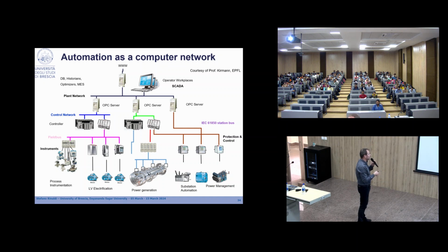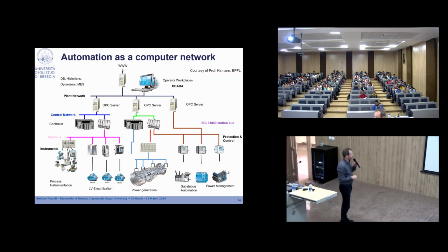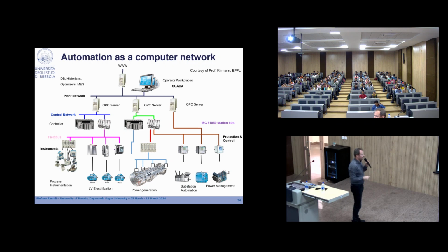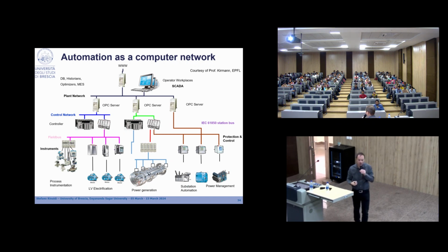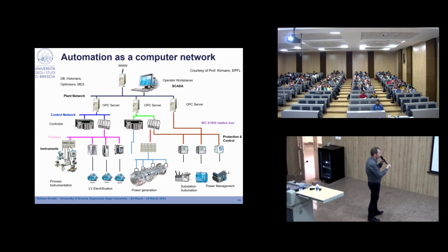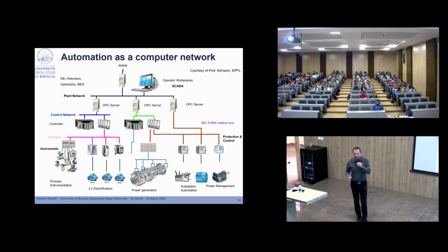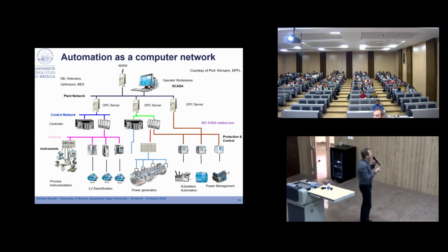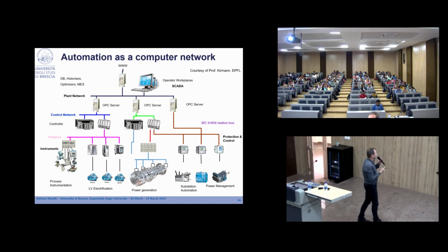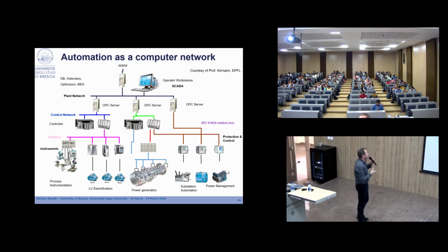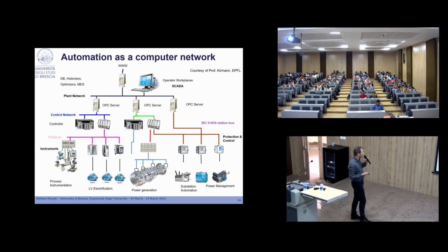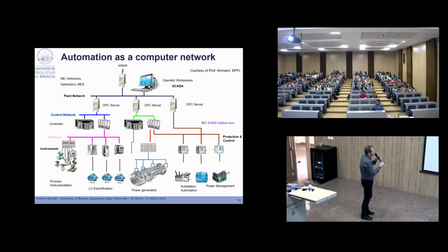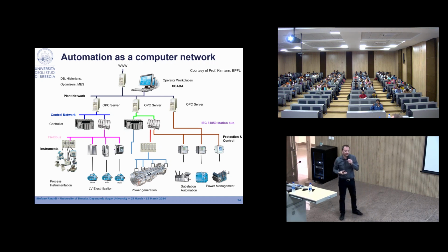It's a communication bus for the field level. The network used for the communication of data between PLCs is called control network, because it connects devices at the control level. And the plant network connects the SCADA system with the PLC. Nowadays, the plant network and the control network in modern plants are the same.